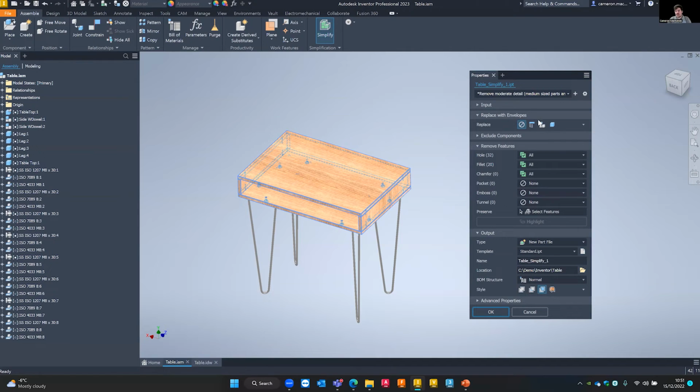Then right down at the bottom, we've got the ability to choose how the solids are treated. So if we're doing it with envelopes, it wouldn't matter as much necessarily for this, but in this case, we're using still the same parts. So we can decide on how we want those parts to be configured going out of this. Do we want all of the single bodies that are in contact with each other to be merged into one solid object? Or do we still want to see that there are separate bodies inside of this? So if somebody had to go and take a section of this view, would they still be able to see where the individual parts merge together or intersect with each other? We can come in and see in between them, but we'll still see the individual items.